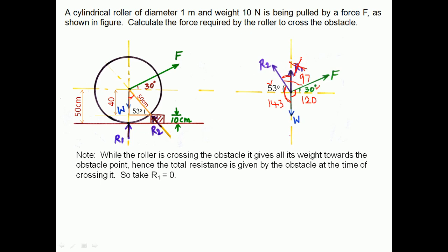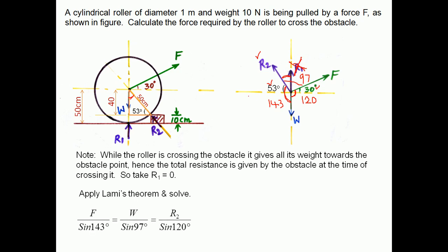After finding this, fit the data in the sine law, Lami's theorem. What are the 3 forces? R2, F and W. So R2 divided by sine 120 equals F divided by sine 143 equals W divided by sine 97, which I have written here.